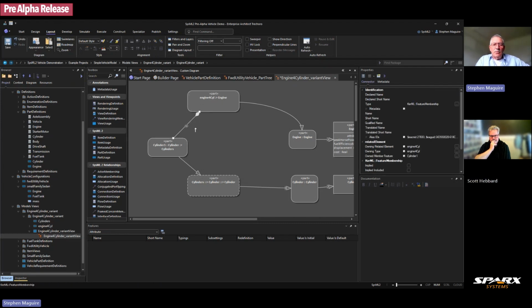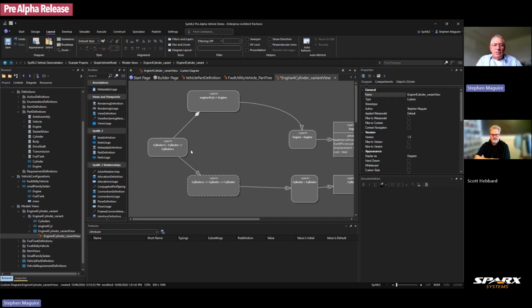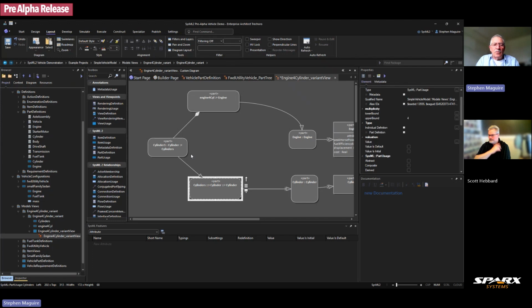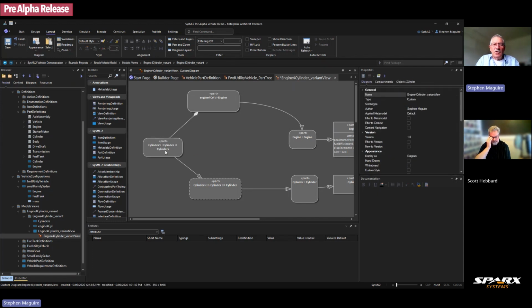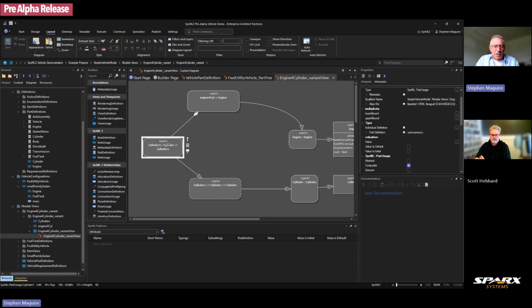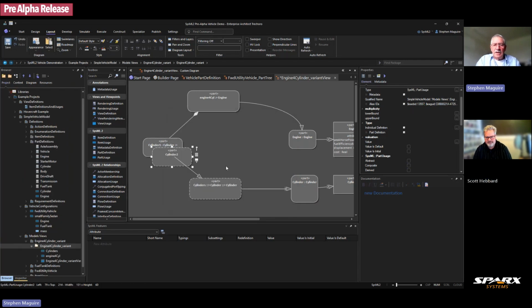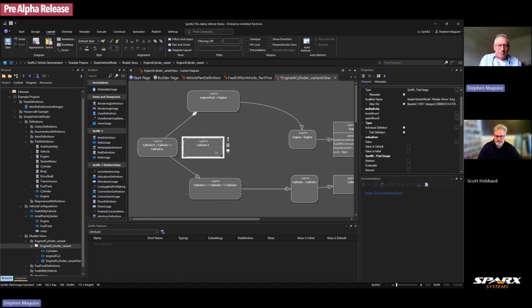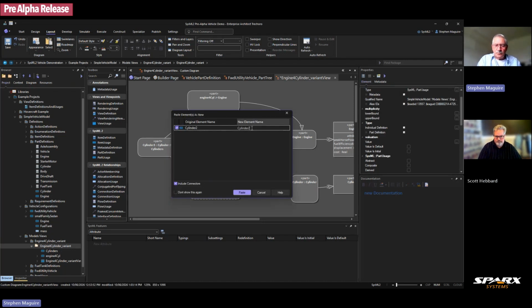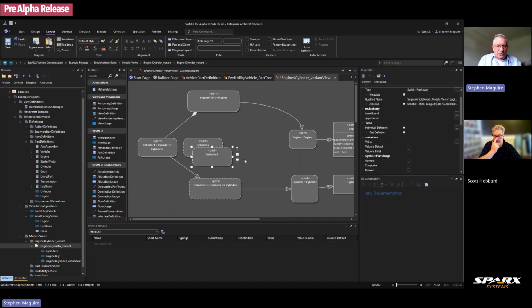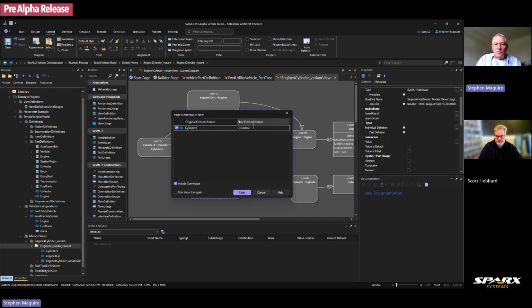So careful to get those around the right way. And now we can simply just go through now and fill out the rest of our model by putting in these different cylinders. And I can do that quite easily, Scott, by just selecting this one here. I'm going to go Control-C on my keyboard and Control-V. I'm going to change that one. So I've got the opportunity to create a new element, element 2, again there. I'd have to go through a series of steps, but let's just do that again. So, Control-C, Control-Shift-V, and again, cylinder 3. Yeah. And again, the same thing for Control-Shift-V and cylinder 4.